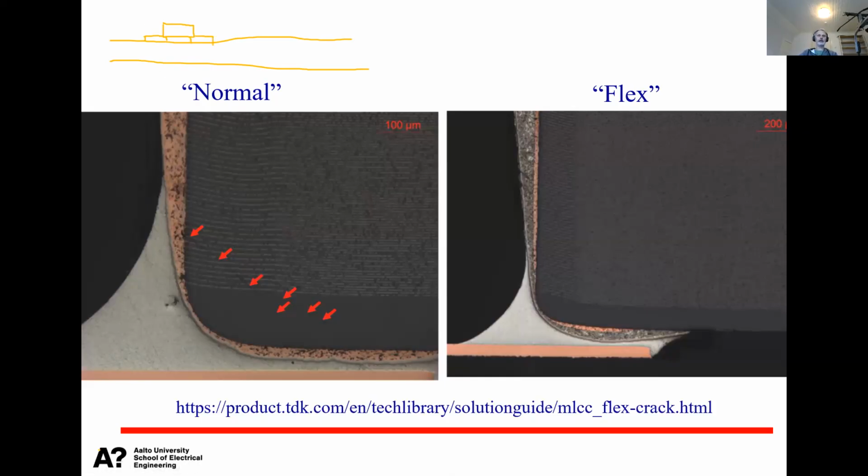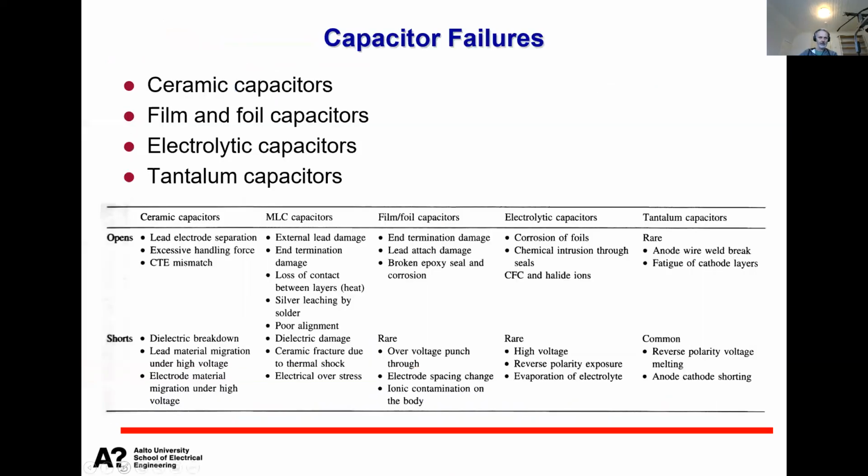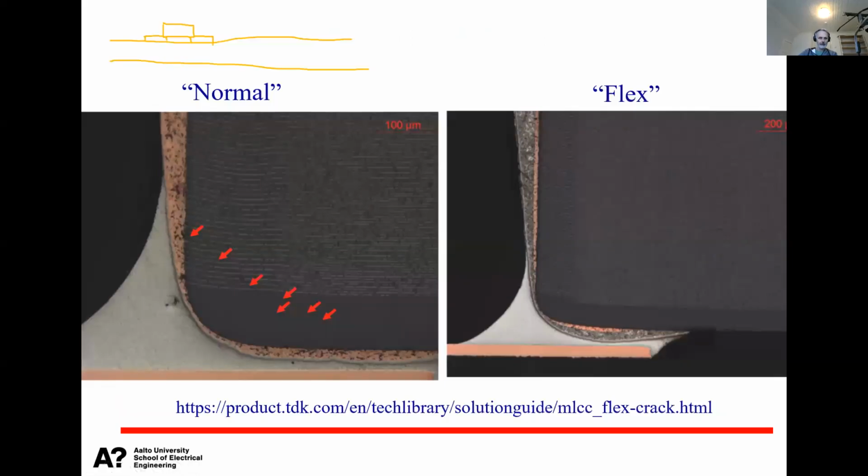You cannot, like in that previous resistor, if I draw with the red color the solder interconnection which we saw in the resistor in the previous case example, the idea there was to have as large a volume of solder as possible. But ceramic capacitors are mechanically quite fragile. So there are design rules for how large the solder interconnections can be.